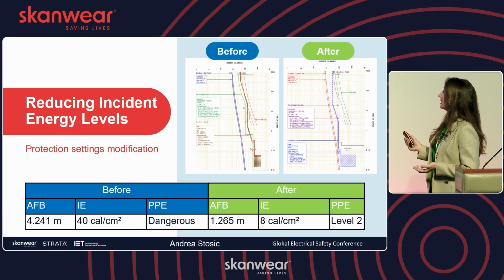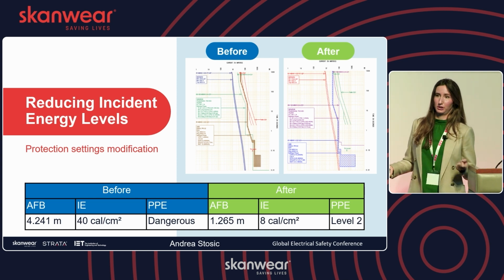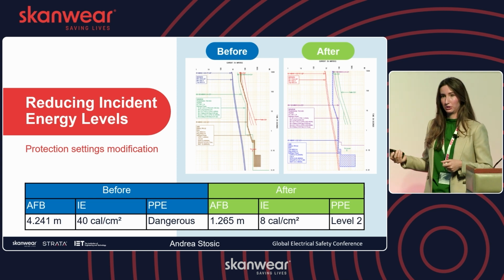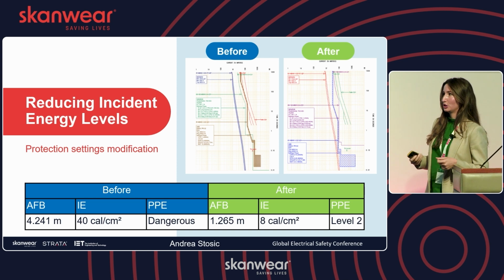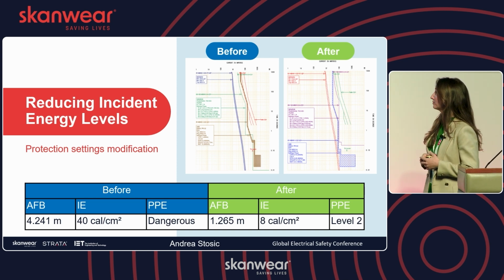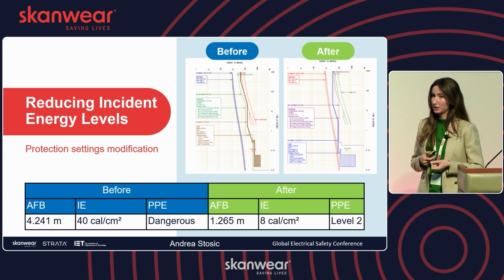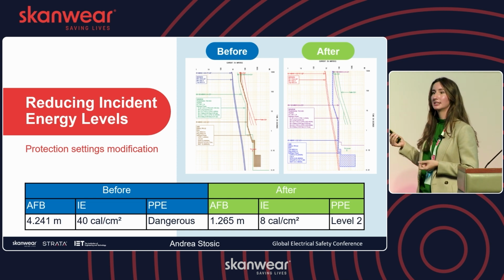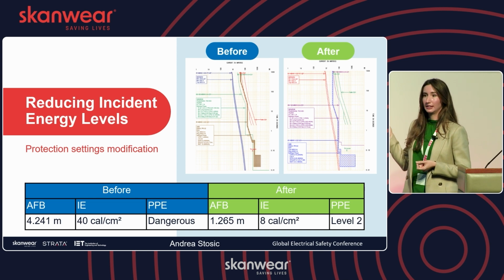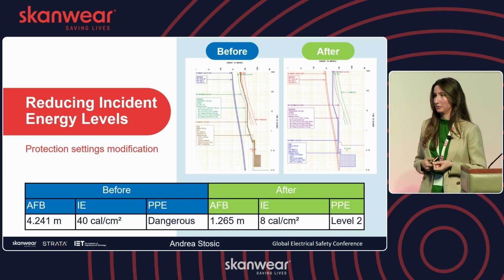When we made the protection settings tweaks, and we mainly changed the protection settings of the low voltage incomer and the medium voltage relay, we managed to significantly improve the situation. So now you can see we have a PPE that's rated for 8 calories per centimeter square, and to be precise, the incident energy achieved now was 5.28 calories per centimeter square.